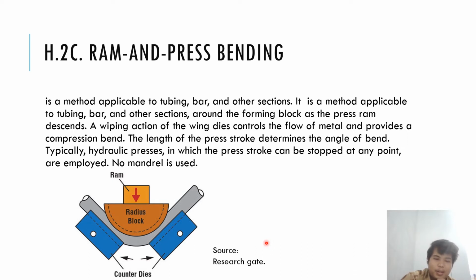No mandrel is used. So it's going to be fit into here, and the ram is going to push to make the bending, and the counter die here, like we have learned about press bending, is going to be pushed by the ram. The counter die is stationary or not movable, and it's going to stay until the workpiece is bent.